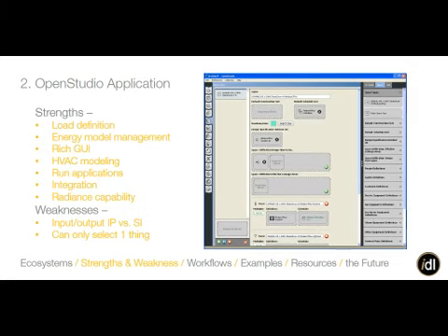Does it go into California requirements? EnergyPro is designed around California, so it spits out what you need for the compliance. That's one thing, it's really just the bare results, and even if you want to try to take this into LEED, you have to translate everything manually. There's a couple of programs and plugins out there that can help shape those outputs towards Title 24 compliance or towards code compliance, but generally it's just the bare outputs.